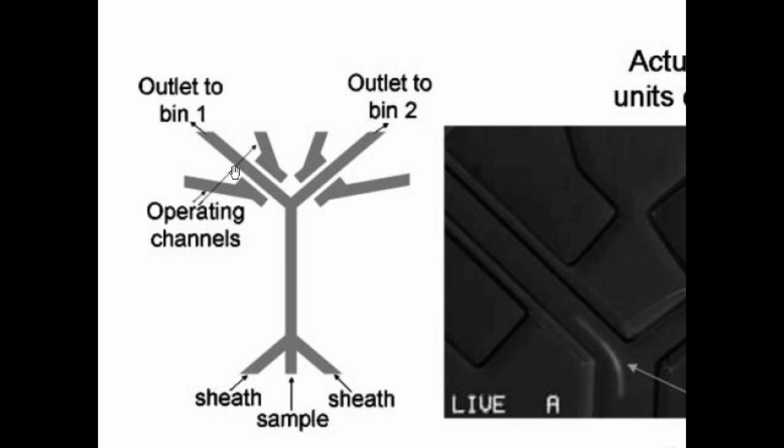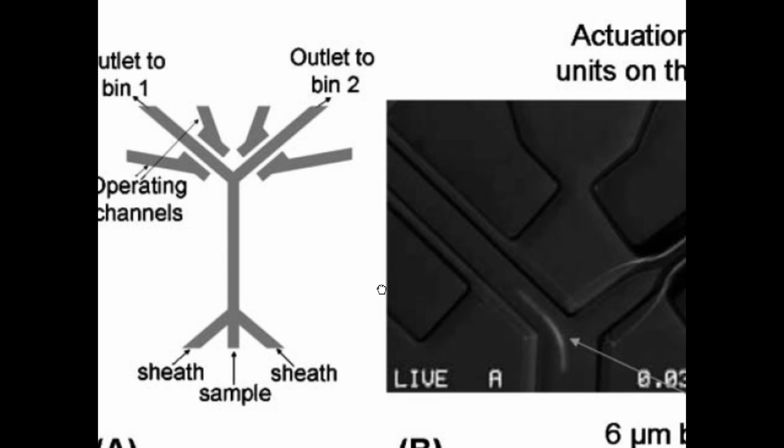This is your fluid channel, and these two things here are your pneumatic control channels. When you apply a positive pressure here, it causes the membrane, meaning the thin wall between the gas and the fluid flow layer, to bend this way. When these two bend, it can close off the microchannel. So this is a very simple way to get valves in a single layer device.